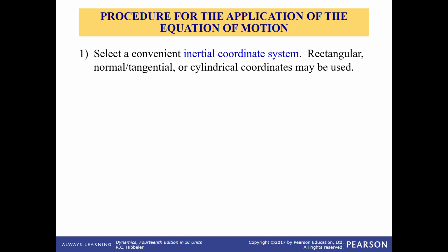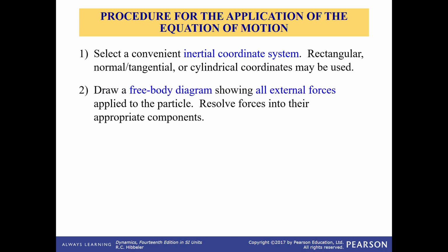Okay, this is the procedure for the application of the equation of motion. First, you need to select a convenient inertial coordinate system, either rectangular, normal and tangential, or cylindrical coordinates may be used. Second, you need to draw, and this is the point that students always miss, a free body diagram showing all external forces applied to the particle.